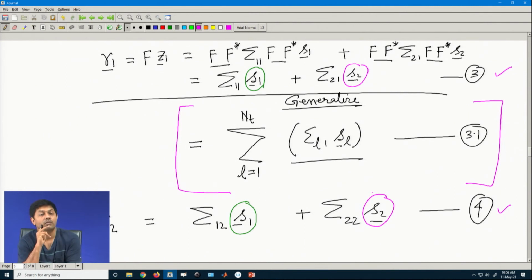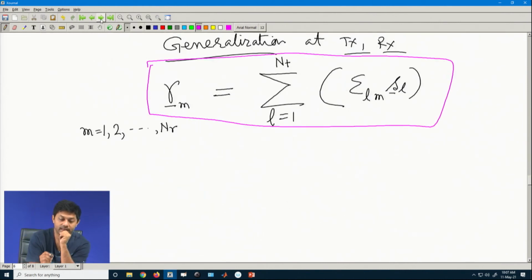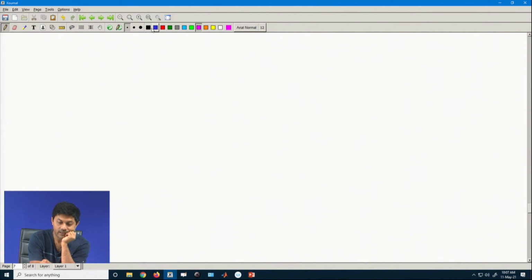So, that was the case for single antenna OFDM case, SISO OFDM case. There you just receive a data, then what will happen? You take the vector, take the individual point, I mean the say ith element of R vector, and I can decode it like a normal AWGN channel, but this is not the case. If you take the ith, let us take the ith, say R1 vector's ith data, what it will contain? It will contain some.